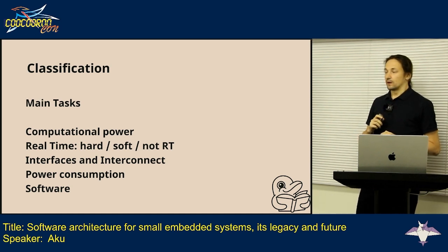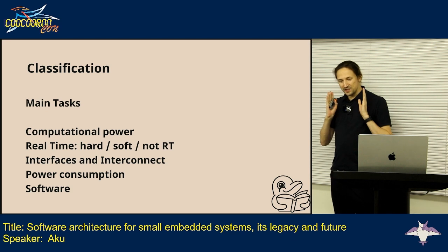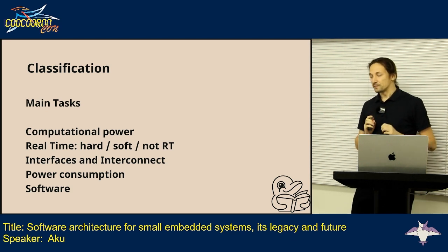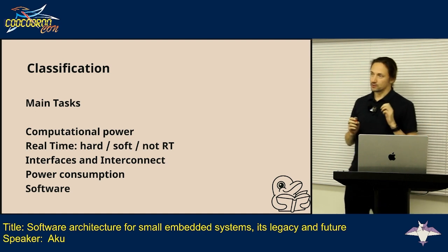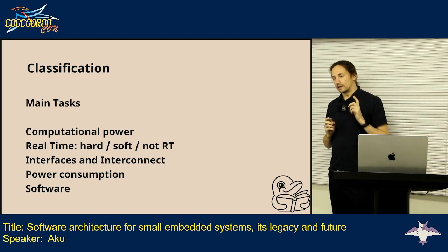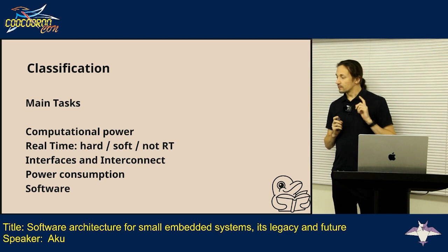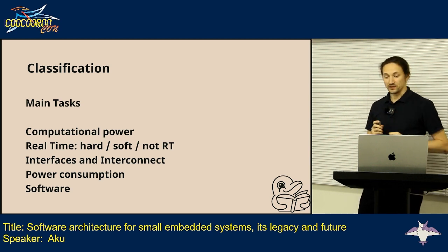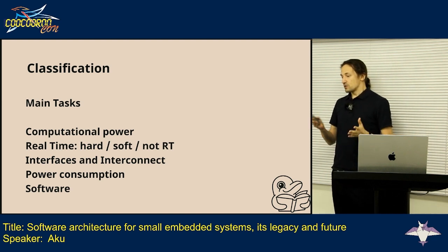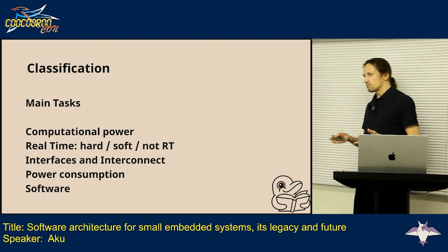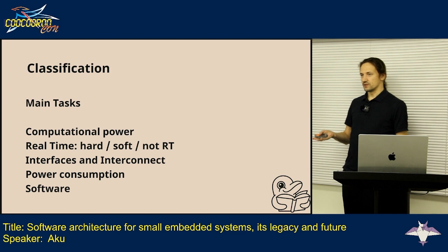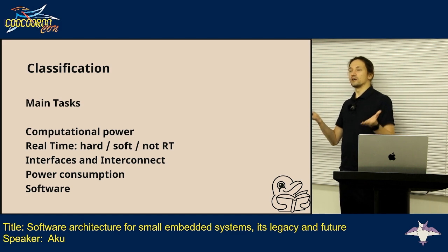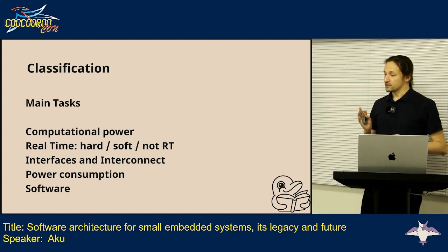Plus, there is a special kind of architecture designed specifically for real-time tasks. It's called ARM-R, and that's what you would probably want if you're designing hard real-time things. Soft real-time usually means that if you miss a deadline, the system is not going to crash. Let's say it's not a plane, it's not going to dive and crash.